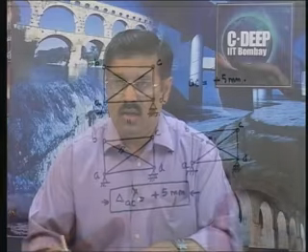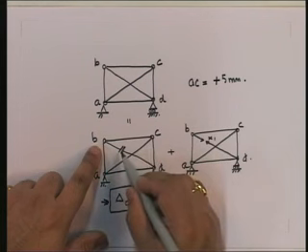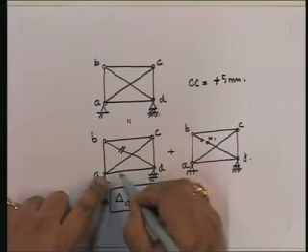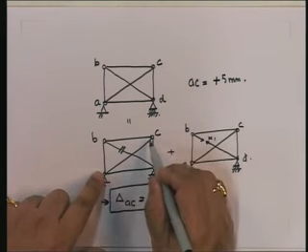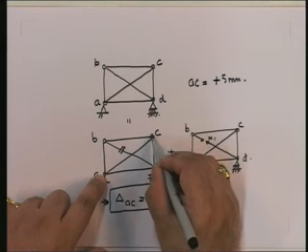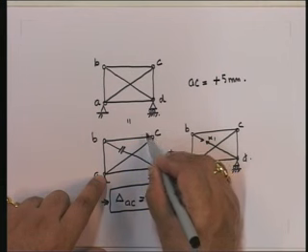Now what I need to do is find the effect of this deformation. Note that I still have this 3, 4, 5, and this cut that I made was in the 3, 4, 5 triangle. Now suddenly AC is longer. So what's going to happen is, this point cannot go anywhere, and to ensure that this is longer, this will have to move somewhere along this direction.